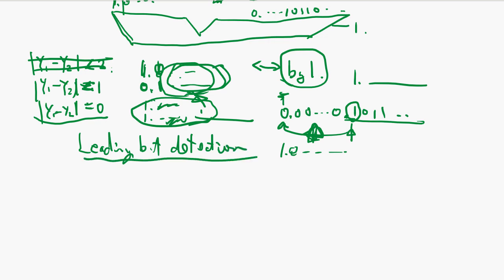And this logic design is a little bit of a problem because you don't know how many bits are 0. If you try 1 by 1, it costs 1 clock each, and with 64 bits, this is going to be a very slow floating point unit. Okay, so in order to use a pipeline, we assume 1 is here and assume 1 is here.